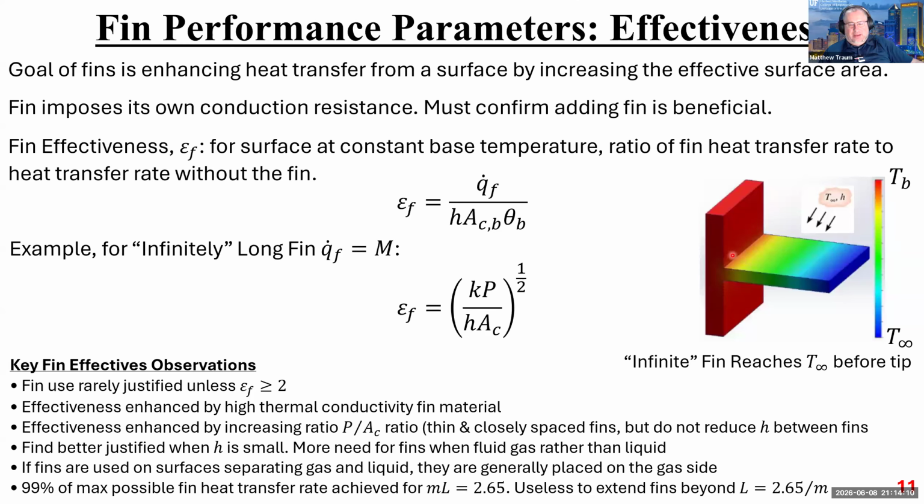There is some length of this fin, probably right about here, where the fin's temperature has reached the temperature of the ambient environment, in which case there's no more temperature gradient between the fin and the environment. And so there's no more heat transfer between the fin and the ambient environment. All of the length of the fin past the spot where those two temperatures are equal is basically useless. It's kind of like a dead fin.